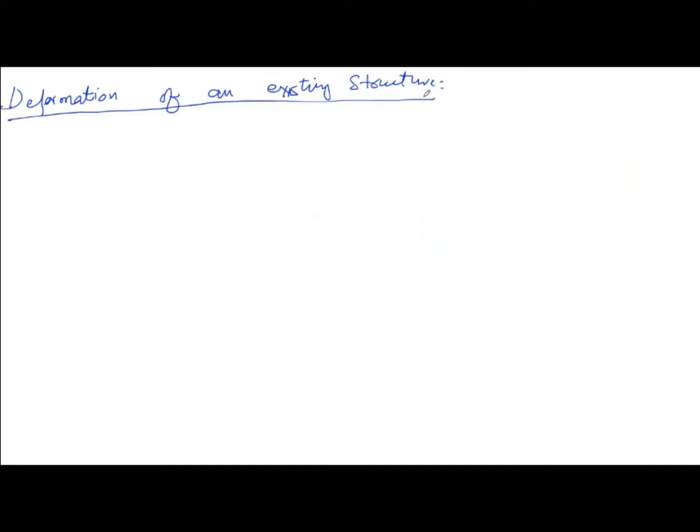So what is carried out in the assessment of structures? The initial elastic vibration period, the Tn, and the yield strength, Fy, of the system is determined first based on the properties of the structure. For example, the dimensions, member sizes, design detail, for example, reinforcement in a reinforced concrete structure, steel sections, connections, and so on. So once you obtain these two properties,